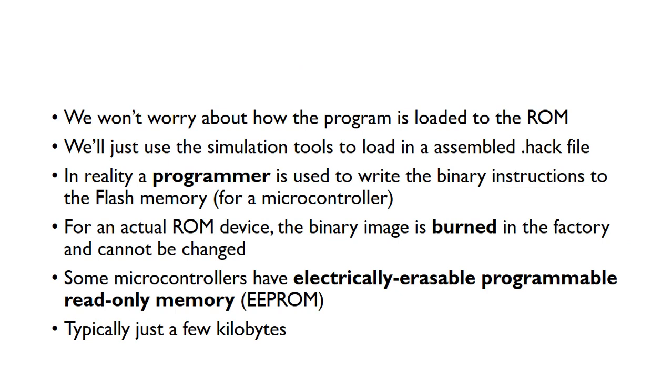At this point, we don't worry about how the program is going to be loaded into the ROM. We just use a simulation tool provided as part of the Nand to Tetris suite to load in an assembled Hack file. But in reality, we have to use a special programmer to write the binary instructions to the flash memory. For example, for a microcontroller, you'd write the code on a computer, compile the code to get the binary file, and then use a programmer to copy the compiled and assembled file into the microcontroller flash memory.